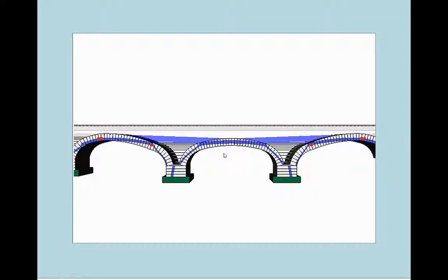And one other thing to say is that because of the sort of pseudo-elliptical geometry, I've assumed that there will be backing elements above the piers. And the amount of backing that I've assumed, it turns out, is quite pivotal to the locations of the hinges.